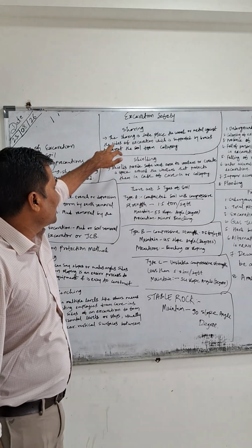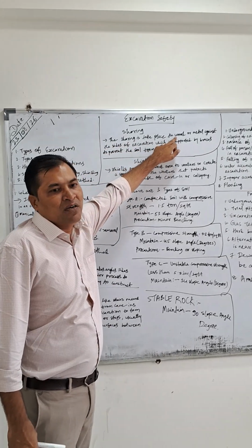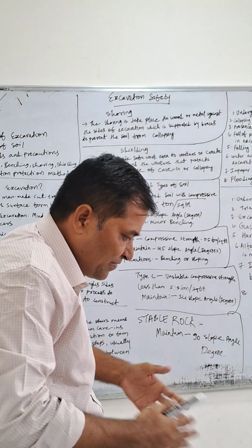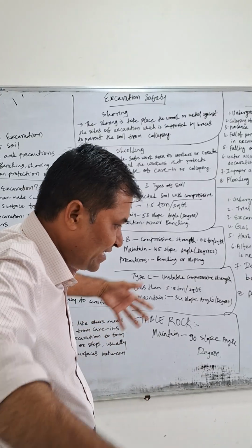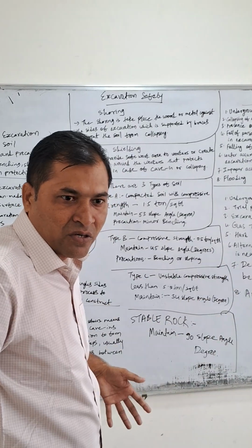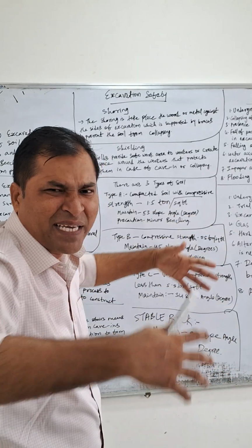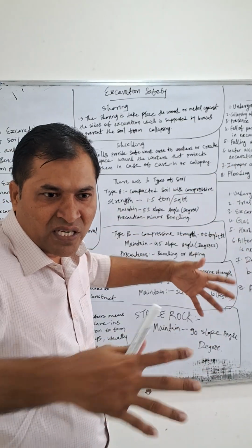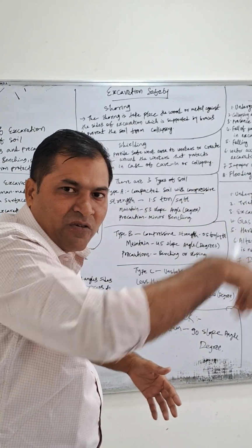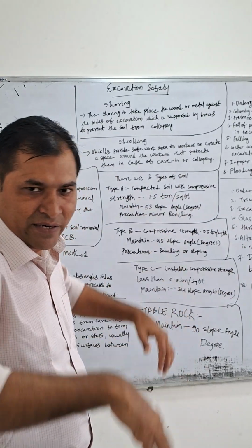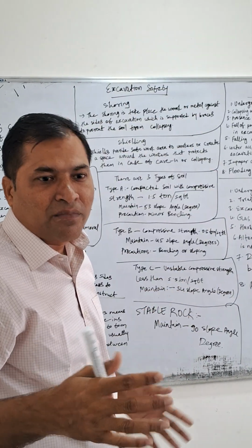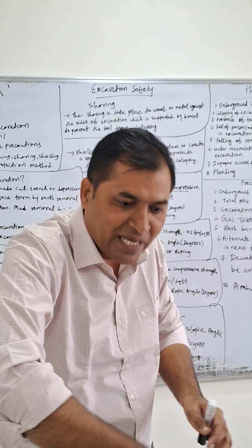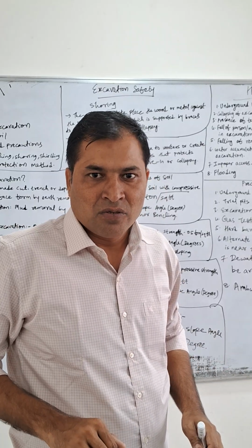Now shoring. Shoring takes place where you can go with wood or metal material. If you dig around 15 feet, the breadth of that hole or the tunnel, whether you are making a tunnel, pits, or a gutter, whatever your digging process is for, like a big gutter or a tunnel, the soil will come down again over there. So it is better to put wood or metal surfaces. The soil which you are putting on top may come down again into the same pit.